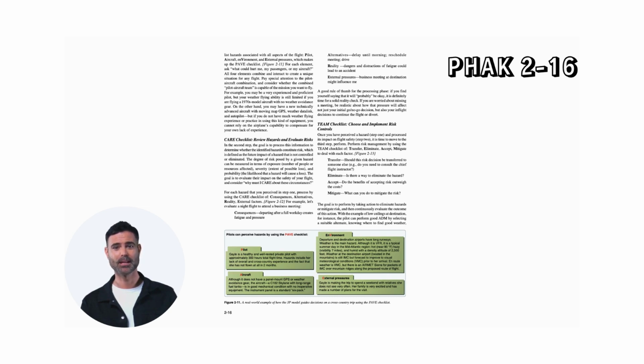For each element, ask, what could hurt me, my passengers, or my aircraft? All 4 elements combine and interact to create a unique situation for any flight. Pay special attention to the pilot-aircraft combination and consider whether the combined pilot-aircraft team is capable of the mission you want to fly. For example, you may be a very experienced and proficient pilot, but your weather flying ability is still limited if you are flying a 1970s model aircraft with no weather avoidance gear.